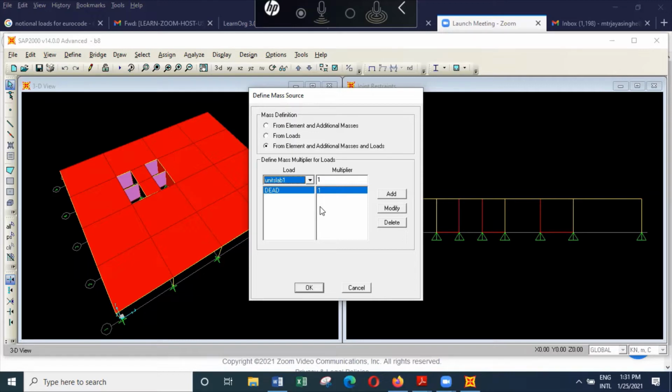So now what we can do is the weight of the finishers can be added. In addition to that, if you think when you are making the allowance for partitions, we are making higher allowance. But in reality, the actual weight could be lower. So if you have some idea about the actual weight of the structure, then again, you can allocate.